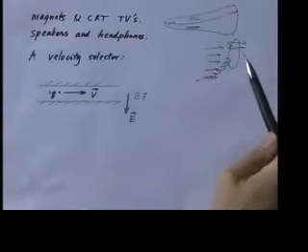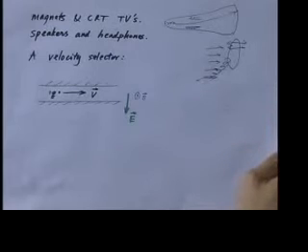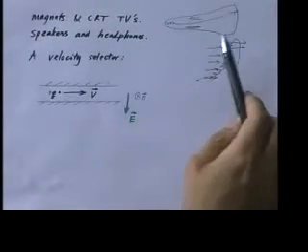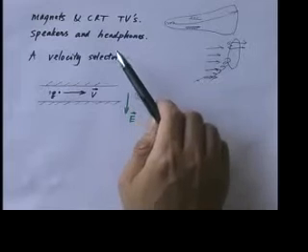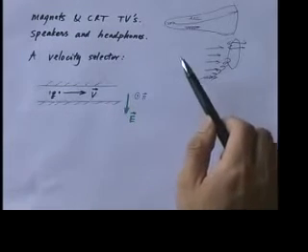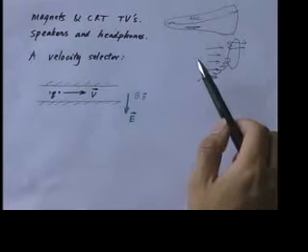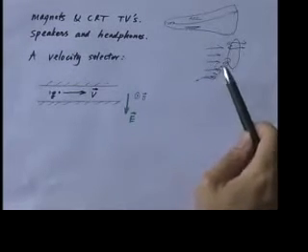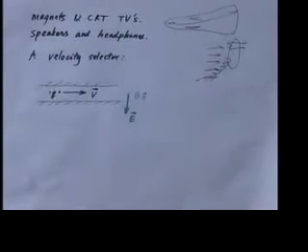So in order to make them coexist one next to another, you need to provide a shield. You need to shield your TV away from the speaker's magnetic field. Modern speakers are usually designed in such a way that they shield their own magnetic field, so that you can put one right next to a CRT TV and nothing would happen. This is an important part of the design of a modern speaker, to shield itself magnetically, so the magnetic field of the speaker does not leak out.